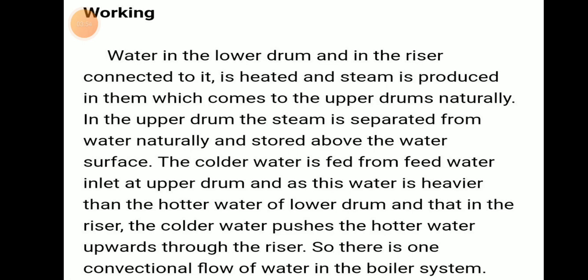Here is the working. Water in the lower drum and in the riser connected to it is heated and steam is produced, which comes to the upper drum naturally. In the upper drum, the steam is separated from water naturally and stored above the water surface.